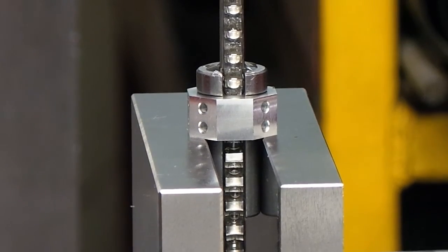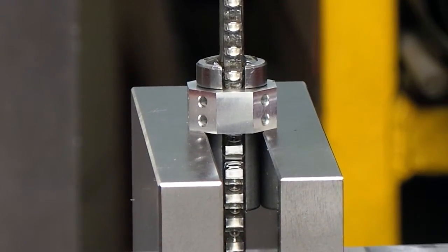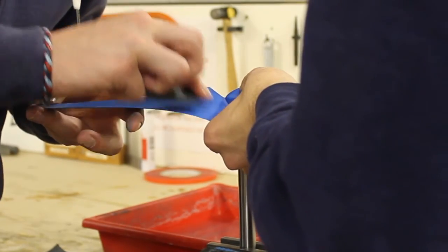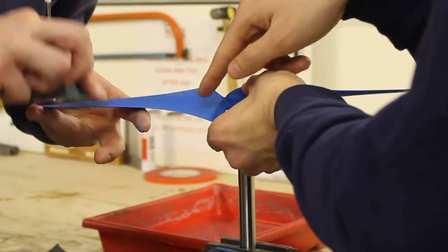2 holes were then drilled into 6 of the sides in an effort to reduce mass, with one final threaded hole being introduced for the grub screw. Finally, the keyway was formed through broaching. The blades were finally sanded to a smooth finish, reducing surface roughness and subsequently drag.